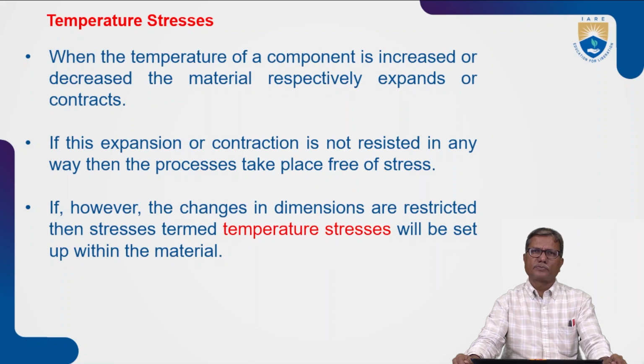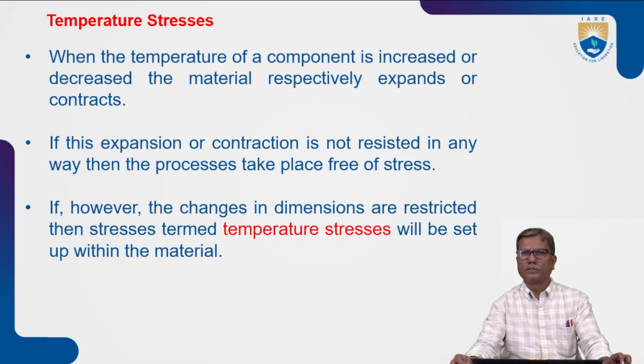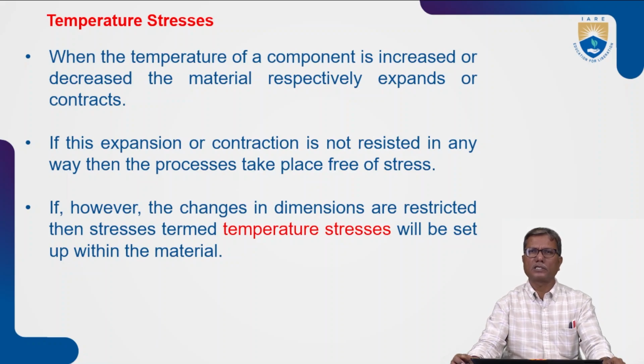If it is free to expand or contract, then there will be no stresses induced due to change in temperature. If the bar is free to expand or contract, no temperature stresses will be induced. When will the stresses be induced due to change in temperature? Only when the bar is restrained from expansion or contraction.